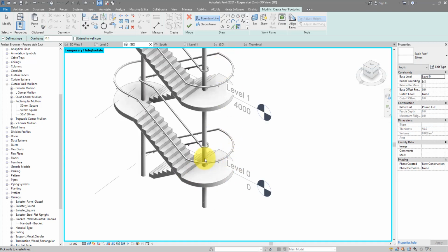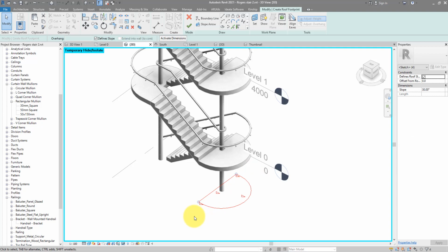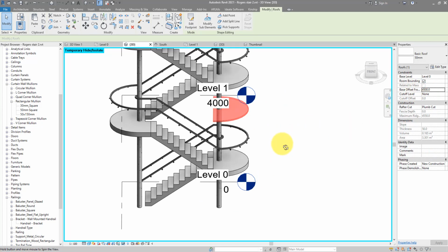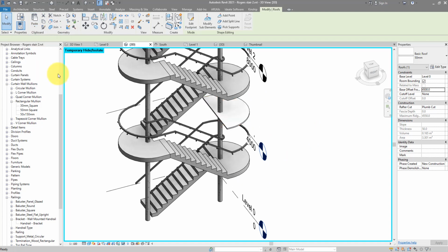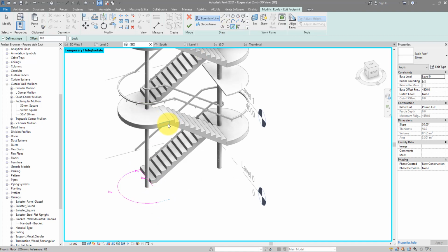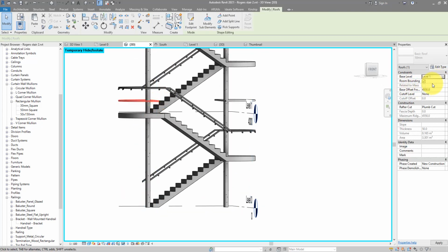For the sketch, I will start picking the boundary of this floor. And then make sure they connect as well. There's no slope needed, so I will select everything there and then turn off define slope. Here we go. We can now copy it to the same place and then edit the sketch of the copy. This time I will pick the boundary of the opposite floor, this one here. And without any slope. This one actually should be on level 1.